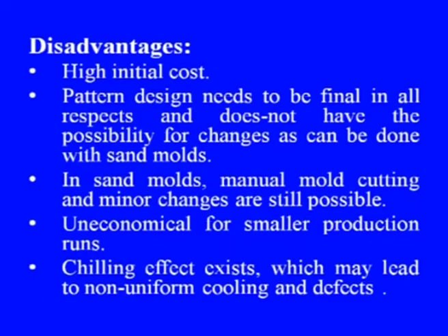Now, let us see the other sides of this process too, that is the disadvantages of the process. The first and foremost consideration is the process has high initial cost. The pattern design needs to be final in all respects and does not have the possibility for changes as can be done with sand molds.